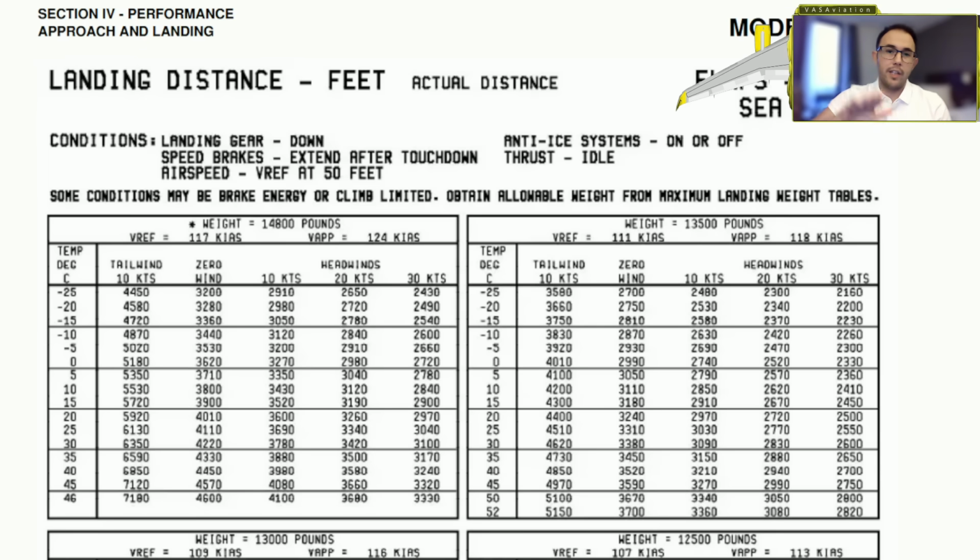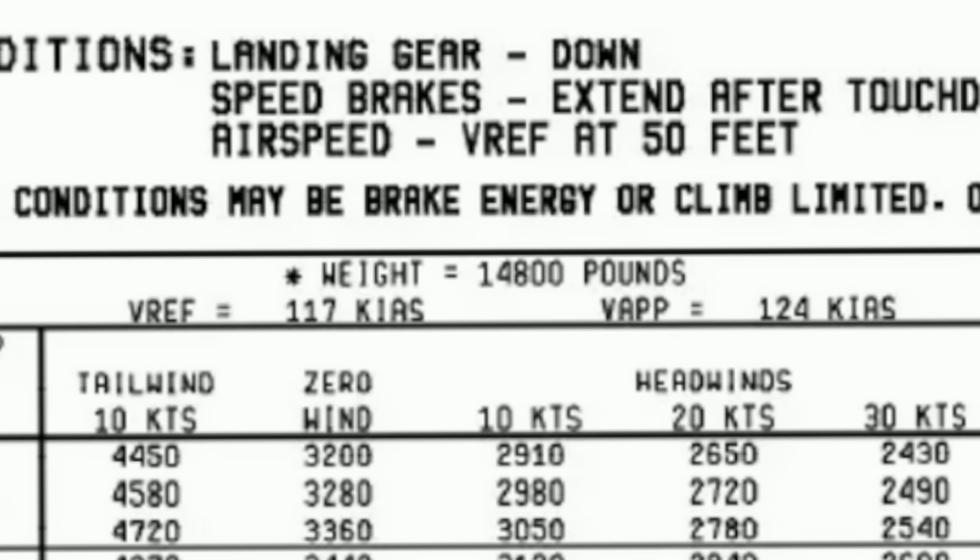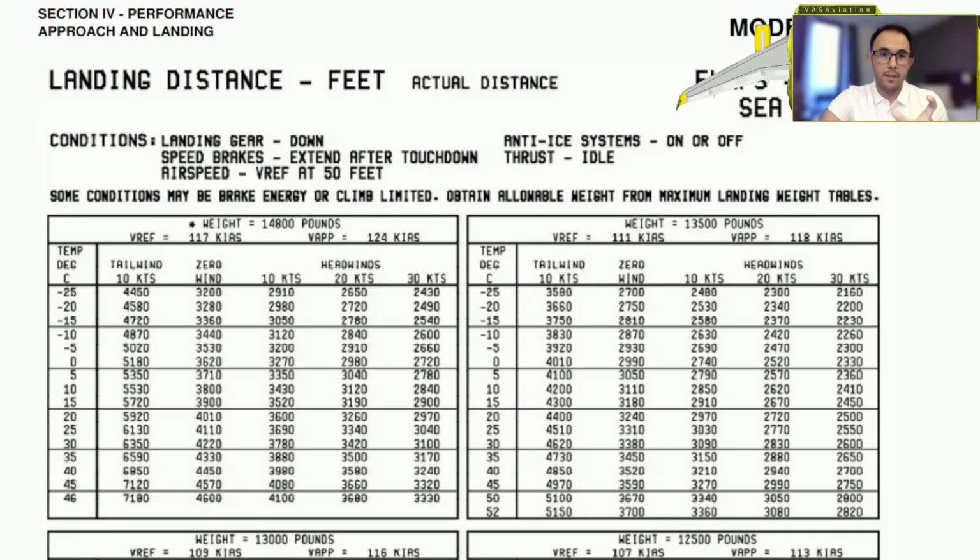Now imagine we're on a takeoff at our maximum takeoff weight, we have a catastrophic emergency, and we need to return back to land. Even with maximum takeoff weight, our VREF is higher, of course, but it's 117. Even in that situation, we are still falling into category B and not C. Our VAP, however, is higher than 120 knots, but VAP is not what the approach categories are based on.